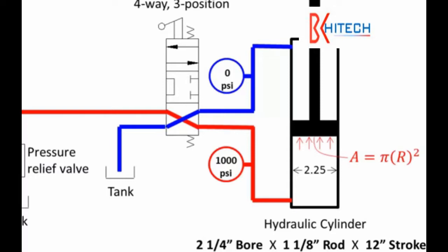But engineers realize that they can't measure radius directly. They have to measure diameter first and then divide by 2. So engineers will adjust this equation to reflect the diameter instead of the radius. And diameter over 2 squared would be the diameter squared, and the 2 also squared, becoming a 4. So this is the equation engineers usually use for area, pi d squared over 4.